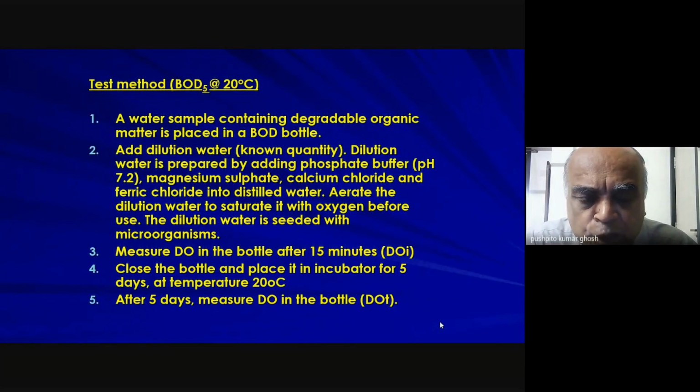So the BOD measurements usually take quite long, and it is quite common to measure it after incubating for about 5 days. After that you see what is the depletion in the oxygen concentration in your solution.